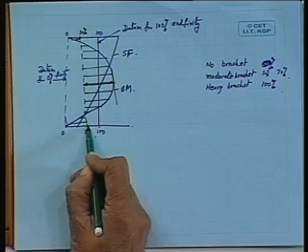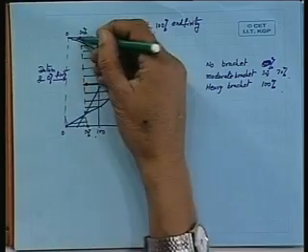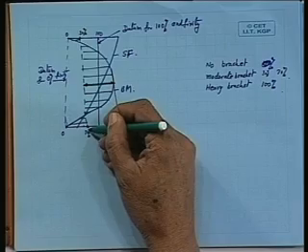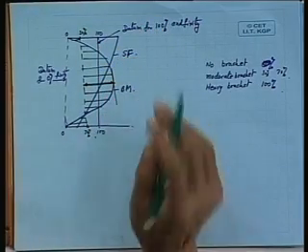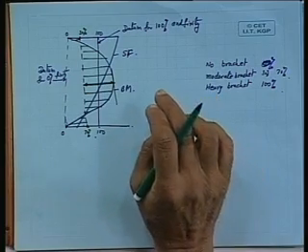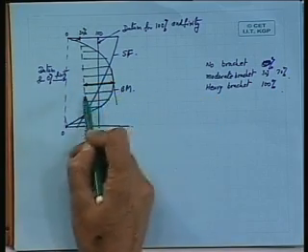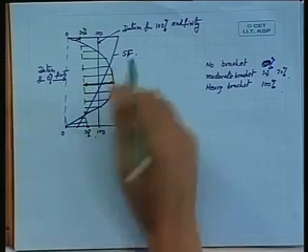So, this is 0, this is 100, proportionately I take 70% here. This is 0, this is 100, proportionately I take 30% here, and then I join these two points to get this line, and this is the datum for the bending moment and the shear force. Okay. So, with respect to this, now I try to find out where the maximum occurs, and how do I get it?